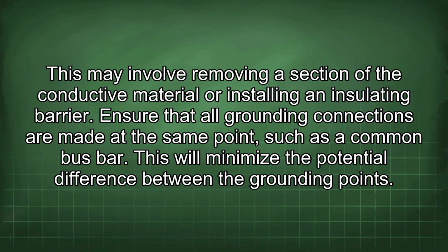Ensure that all grounding connections are made at the same point, such as a common bus bar. This will minimize the potential difference between the grounding points.